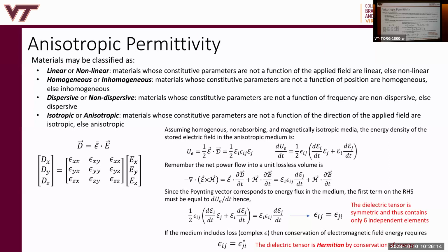How do I do that? I impose boundary conditions on my wave. The cardboard tube imposes boundary conditions. A rectangular waveguide is a metallic hollow pipe, which imposes boundary conditions impenetrable to the electromagnetic field, right? Guided waves have a lot of dispersion. We'll see that when we study rectangular waveguides, and well, I think in a different class, in metamaterials I taught last semester, there's a lot of dispersion relations you derive. So when you study guided wave phenomena, it's all about the dispersion relation.